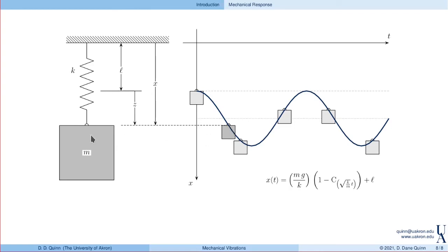This time is shown here on the left, and then it undergoes one complete oscillation after one full period of cosine, right? So that's t is 2 pi divided by the frequency, omega n, or 2 pi square root of m divided by square root of k. So that's the period of the oscillations. And again, that just repeats forever.